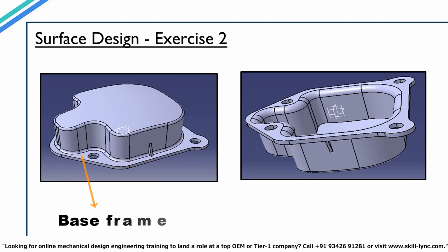This model has a base frame with holes and stiffeners. The model is hollow from inside, so we apply a thickness after creating the surfaces. We will have to switch between part design and shape design workbenches for this model as well.